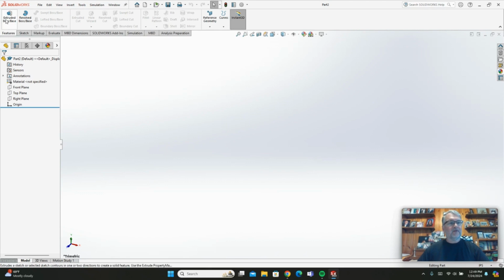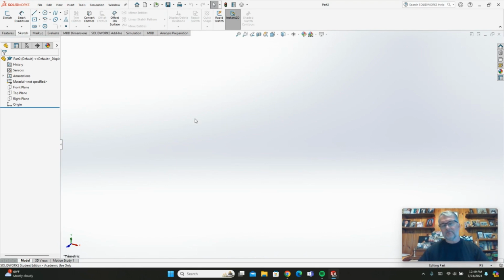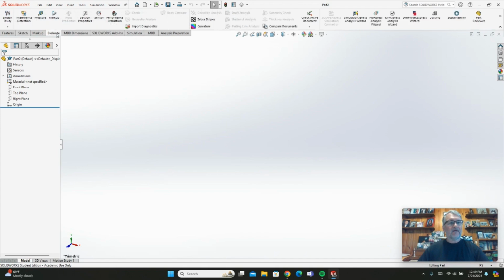You have your features. After you create a sketch, you can add features to it. You have your sketch menu. This is where you start. This is where you're going to do your circles, your lines, whatever you want. This is where it starts. And you have some other features to go along with that. You also have what I like, this evaluate tab. I use this quite often, and the thing that I probably use the most is the measure command, and I'll show you that in just a little bit.